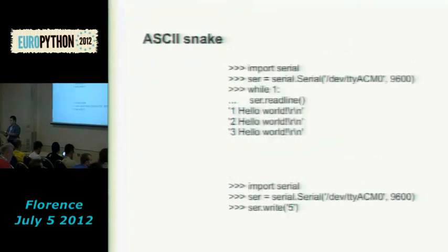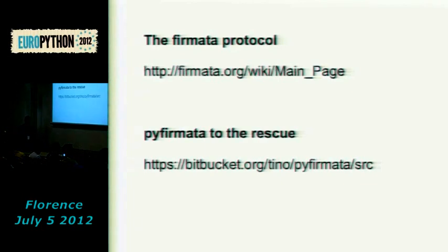But if you want to approach this in a more professional way, you'd better use a proper protocol, like the Firmata protocol. Firmata is a standard protocol for microcontrollers, and you can see the website. It's available for different kinds of microcontroller units. It's a protocol based on MIDI, the protocol used on musical instruments. So it's very compact, it has error checks and has a lot of advantages. It allows you to control every aspect of an Arduino board, and it's also very easy to use.